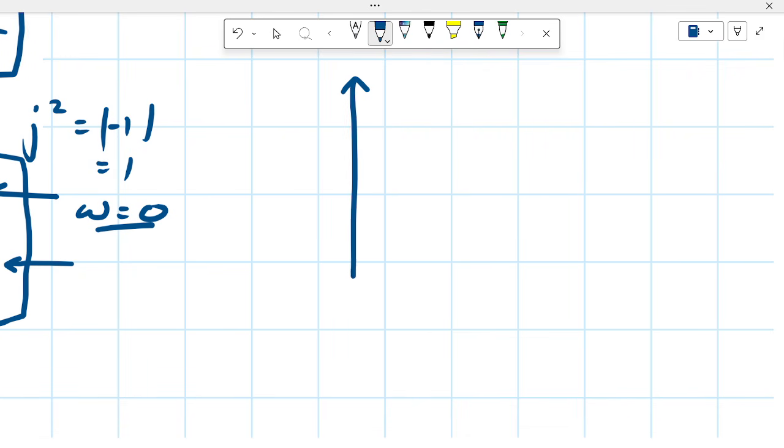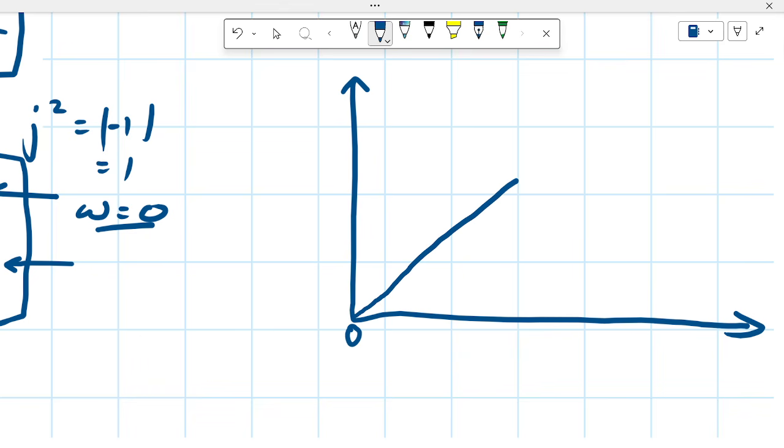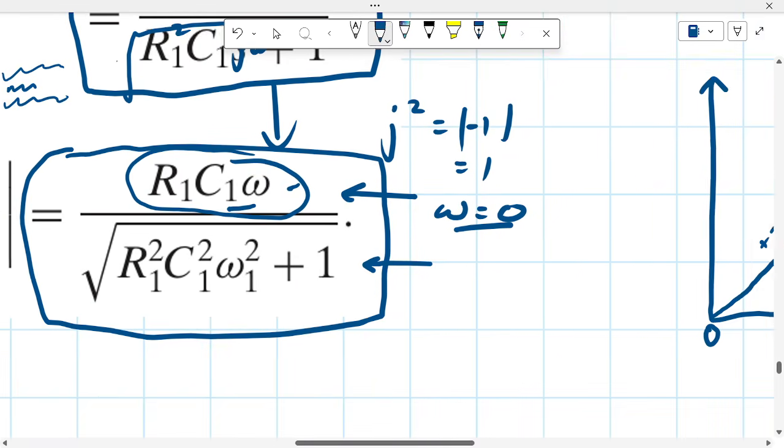And what Bode's rule tells us, or Bode's approximation we could use, is that if the 0 is at the origin, then we increase by plus 20 decibels per decade until we get to a pole. Then when we get to a pole, we reduce by 20 decibels per decade, in which case we are going to get a flat line again, because we're increasing by 20 decibels per decade and we reduce by 20 decibels per decade.